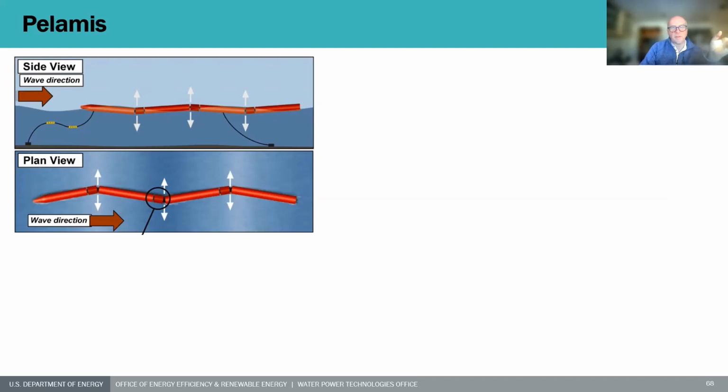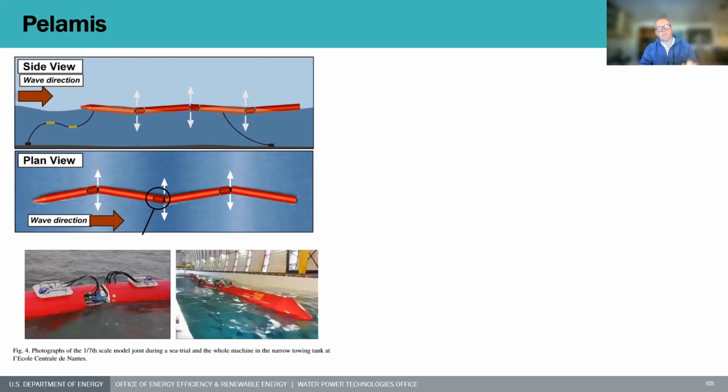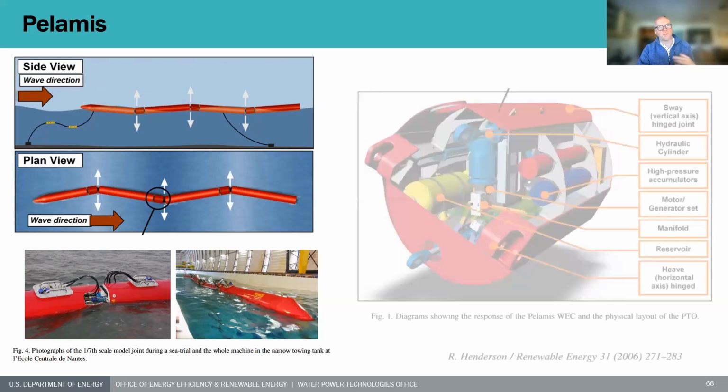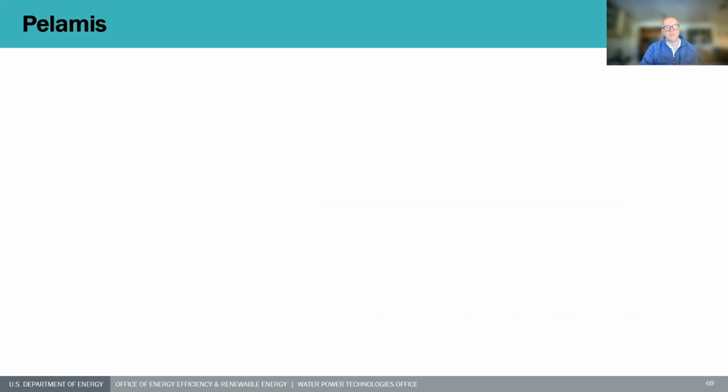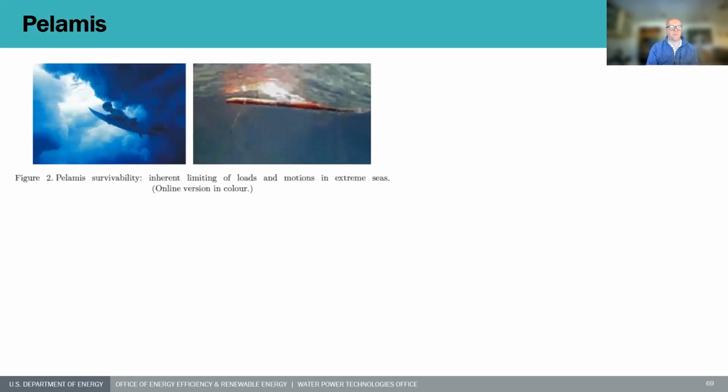So it's an attenuator. The design configuration here, the model of the Pelamis, was opposite to the normal design consideration. When you think of a wave energy converter, you think, hey, what can I do to absorb waves really well? And after that, you think, hey, what do I need to do to make this thing survive. But you can go the opposite way. You can say, I'll choose a configuration that's really good at surviving extreme waves. And one example is to dive through waves. You see a surfer diving through a wave, and this is exactly the same principle that's implemented in Pelamis. So you can dive through a large wave, so you're transparent to the destructive waves.